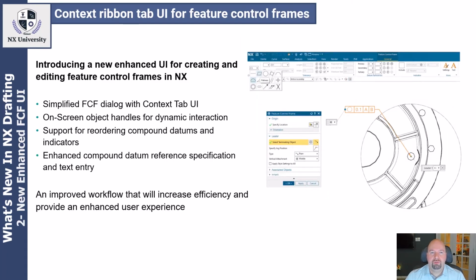Now, with the new feature control frame interface, the software is introducing a new user interface on the ribbon bar. So if I want to create these feature control frames, you're going to see as I enter the feature control frame creation process, the ribbon bar is going to change, and I will have all the tool sets up there on that ribbon bar to build out my feature control frames.